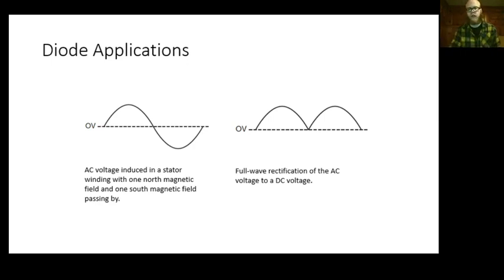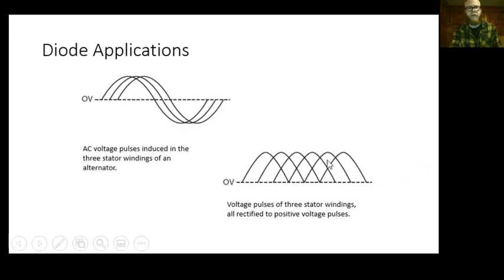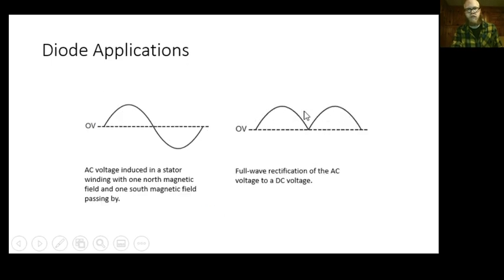the same direction, okay? And the way that we get around this voltage fluctuation that would happen is by lining up 3 circuits from my stator and having enough diodes to control that. So I just overlap them, so I get that little bit of AC ripple, if you remember back. And here we are, 3 circuits overlapped, rectified, and then this little bit of AC ripple there, which is much, much less extreme than what we would see here.